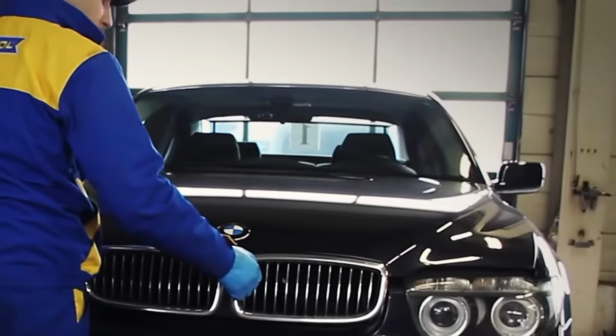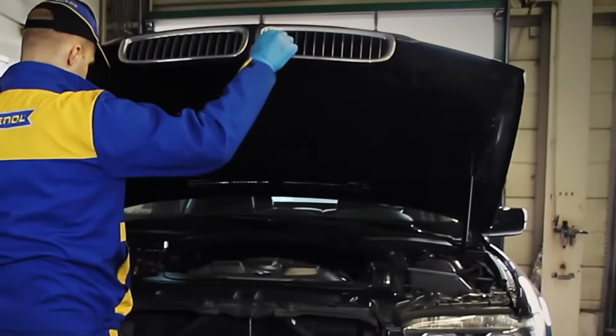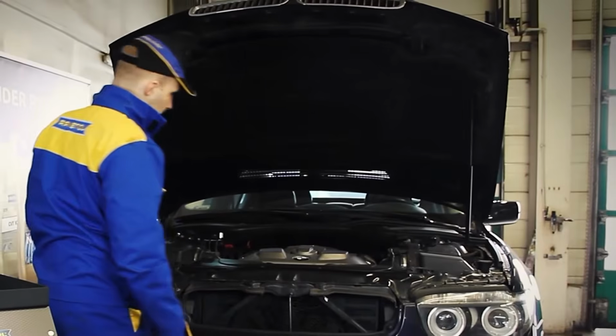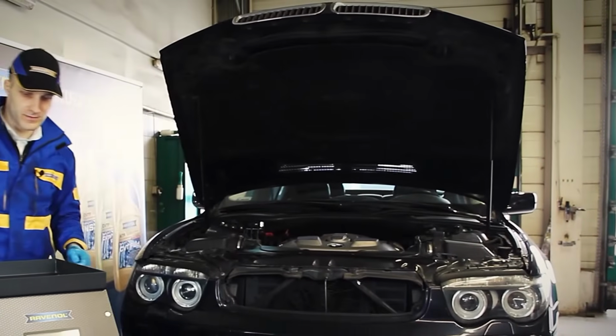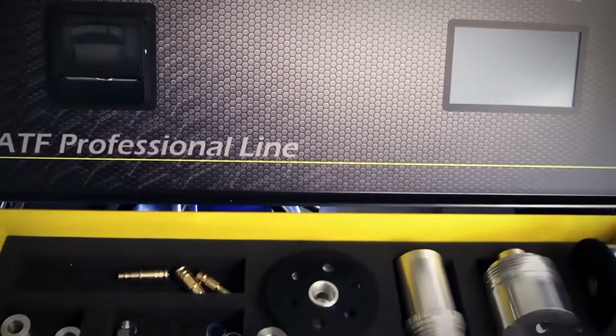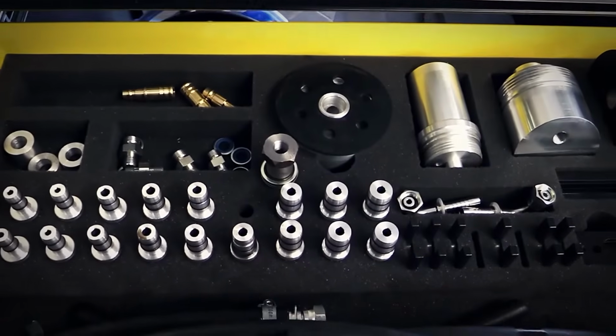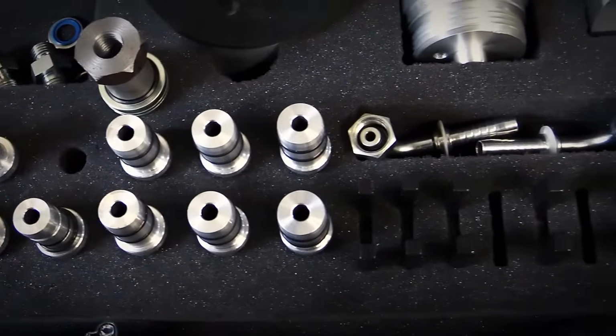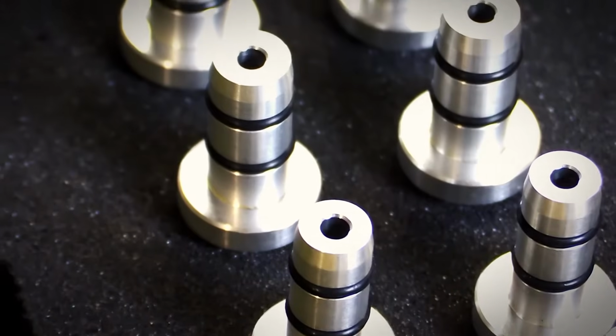The vehicle in this video is a BMW 7 Series E65. The automatic transmission of this model has a fill level of 9 liters. For the dynamic exchange, you require at least 30% more oil. We therefore require a total of approximately 12 liters of ATF transmission fluid. The additional oil is required to flush out the transmission.